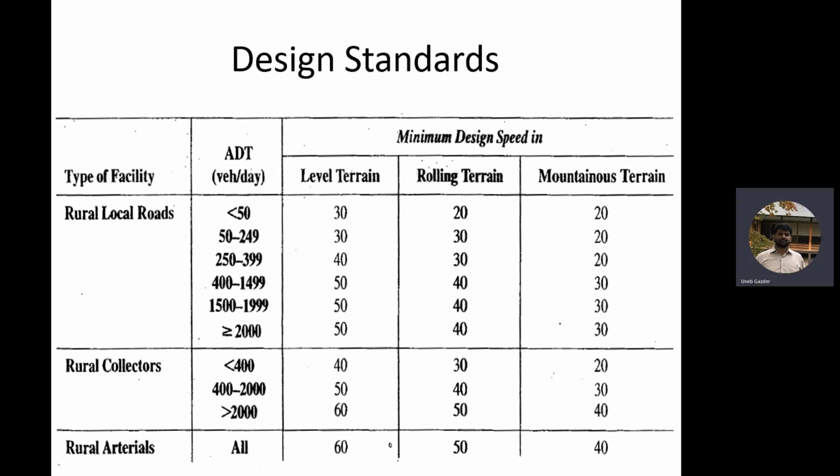So this speed will be found on the road in which conditions? At which level of service? A. And the speed in level of service A? Free flow speed. So these are basically the free flow speeds, not the actual speed of the road when you have this much volume. So free flow speed must increase so the road becomes better in design and can handle more volume. Got it?